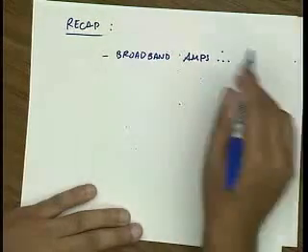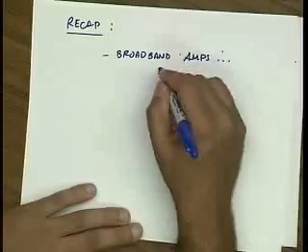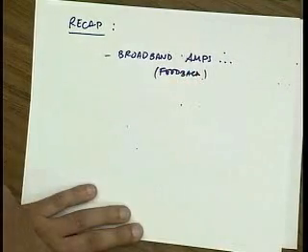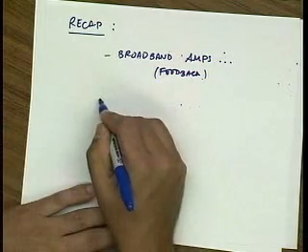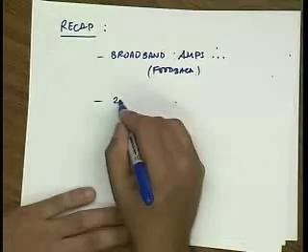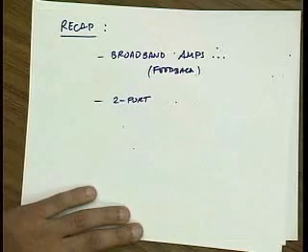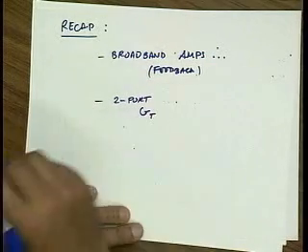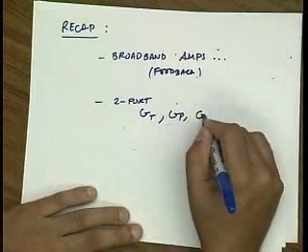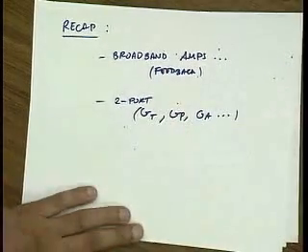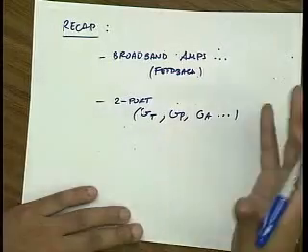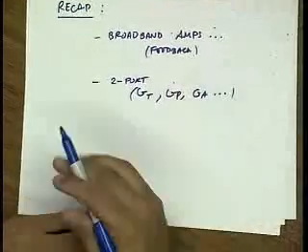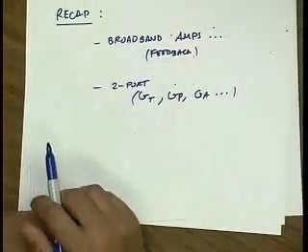So we looked at basically using feedback, for instance, to make our amplifiers more broadband, and so on. Then what we did was we looked at our amplifier as a two-port, right? And we learned ways of maximizing transducer gain, the power gain, the available gain. We did all those calculations, and we found out that actually if you really care about power, then what you should look at is power gain, and there's ways of maximizing that.